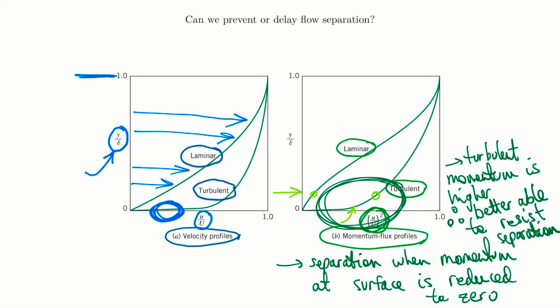So we're going to end here with a qualitative description of separation, basically saying when you have an adverse gradient, it is possible. If you want to know exactly, specifically when, you have to run experiments basically or use some high-level CFD. Or if you're looking at generic shapes, we'll talk a little bit more about this later when we talk about the specific geometries and we look at drag. We'll look at some common shapes, spheres, and cylinders, and we'll talk about what we know about separation in those cases because we do have the experiments already done for very simple geometries, right? We'll talk about that later.